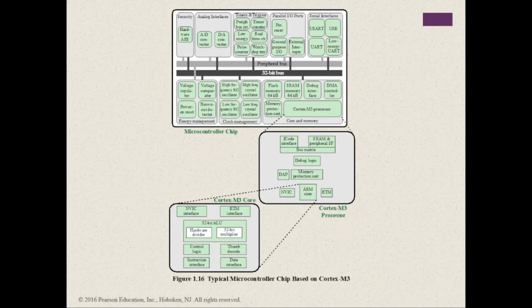The silicon chip consists of 10 main areas, such as core and memory. This region includes the Cortex M3 processor, the static RAM or SRAM, data memory, and flash memory for storing program instructions and non-varying application data. Flash memory is non-volatile, which means data is not lost when the power is shut off, and so is ideal for this purpose. The SRAM stores variable data. This area also includes a debug interface, which makes it easy to reprogram and update the system in the field.